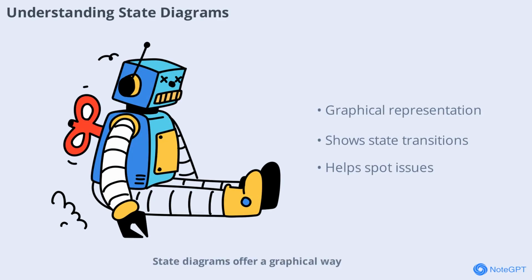State diagrams offer a graphical way to represent the operation of sequential circuits. Each state is depicted as a circle, with arrows showing transitions between states based on input conditions. State diagrams make it easier to visualize the flow of the circuit and identify potential issues, such as unreachable states or unwanted loops. They are often used alongside state tables to provide a complete picture of circuit behavior.